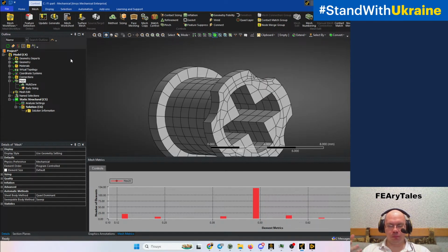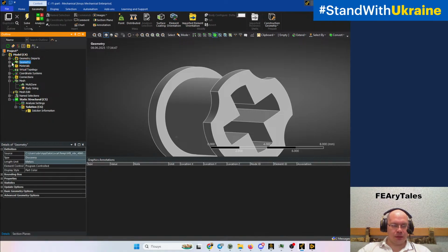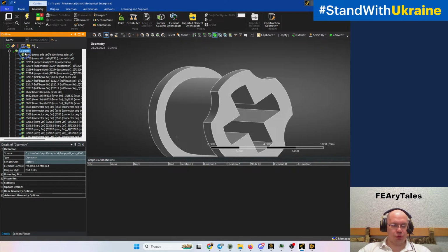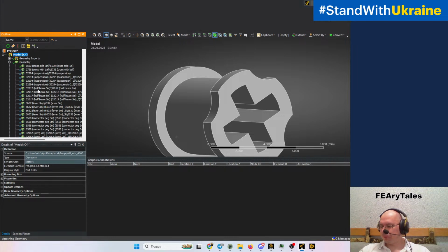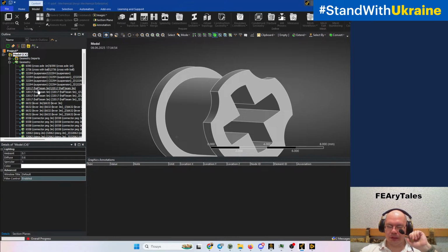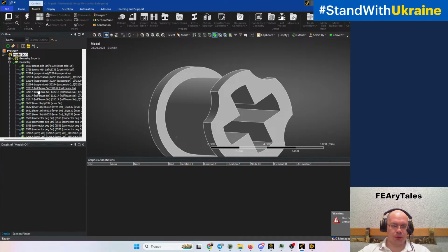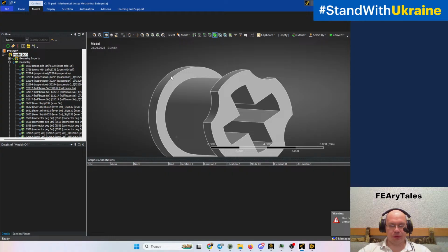It's not for creating a good mesh, but for understanding whether we split our geometry in the right way, or whether we have some problem with splitting, not connected objects and so on. Some objects are not hexahedral, etc.